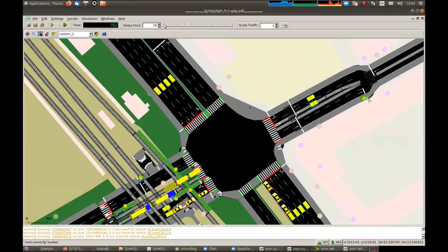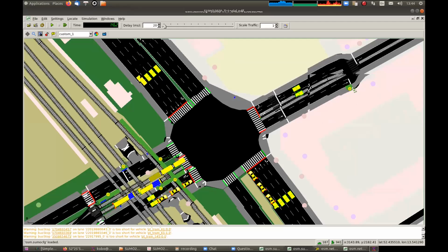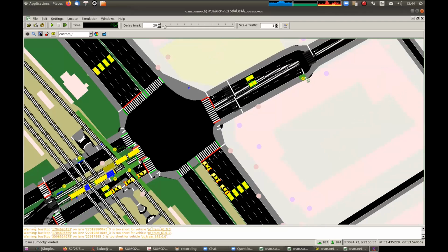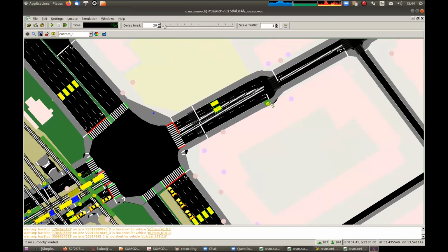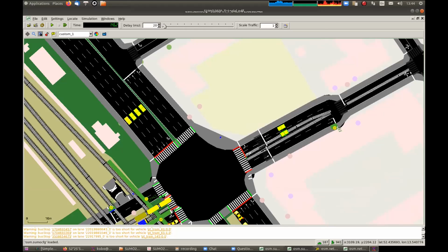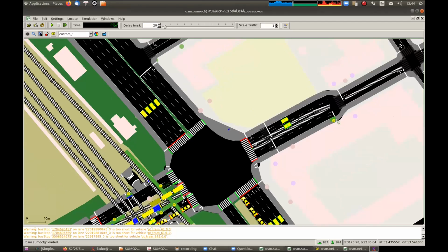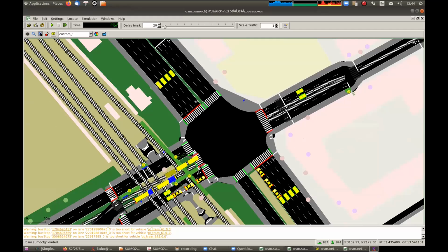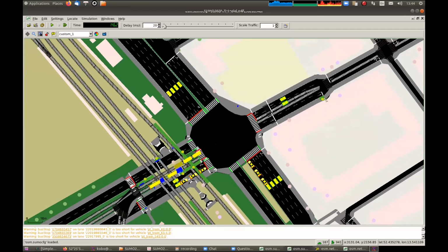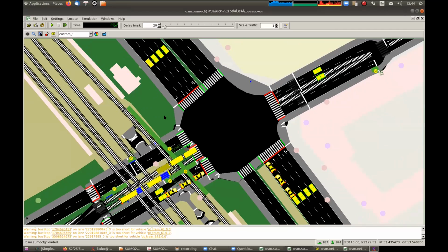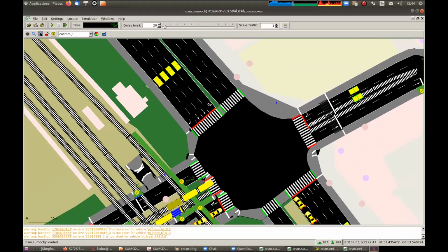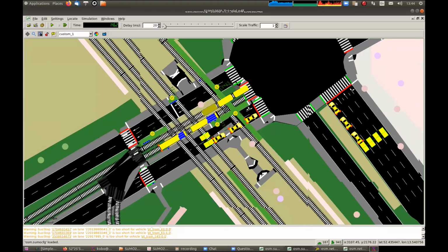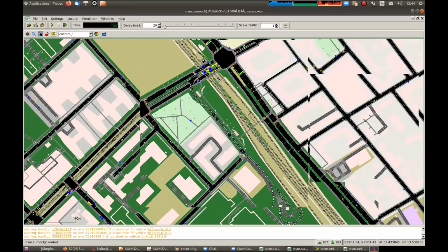These are automatically generated when you define actuated traffic lights, and they control the workings of the traffic light. There's actually a little color code. The green ones are active. The red ones define that there has been a request in the last red period. No red thing here. Oh, the others aren't visible.